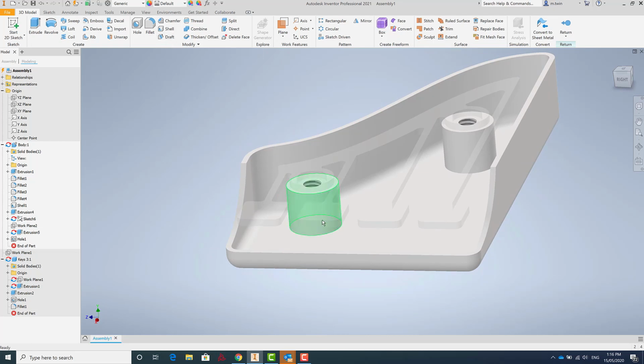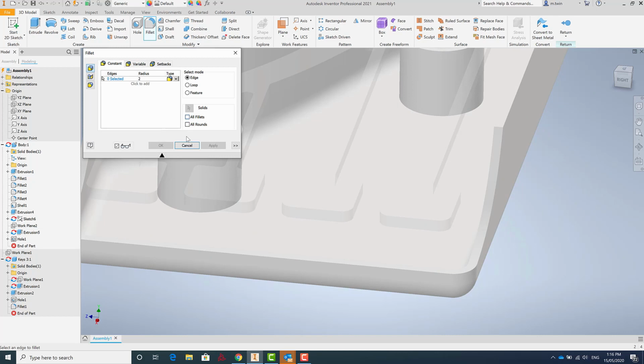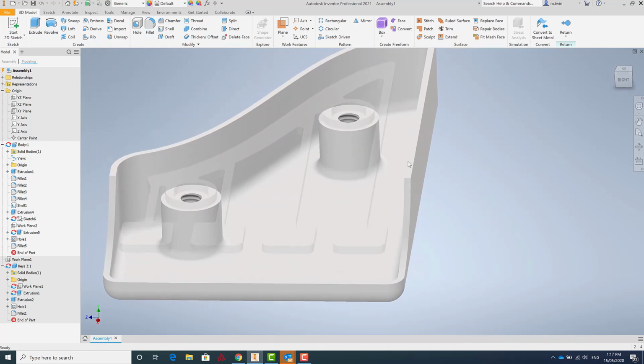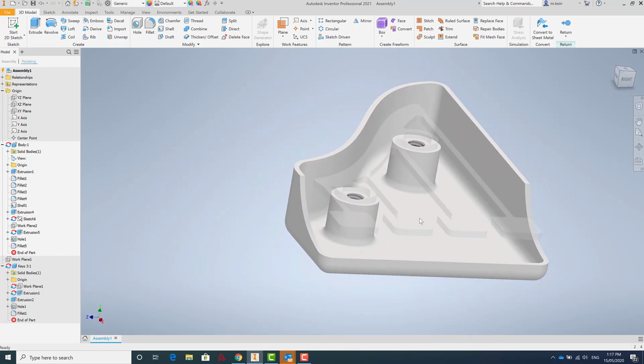Now what I need to do is smooth that interface a bit. It's a very sharp edge down there, and as any engineer will tell you, a sharp edge is a stress riser, and that's where you're going to see a failure. So I'll make that radius probably just 1 millimeter will be fine for this one. That one there. That one there. And we'll apply that. There we go. And now our posts are blended nicely into the base there. And we should still get some nice vibration transmitted through to that base, which means more noise.